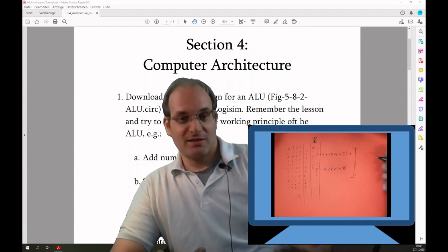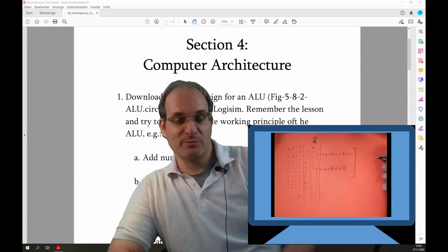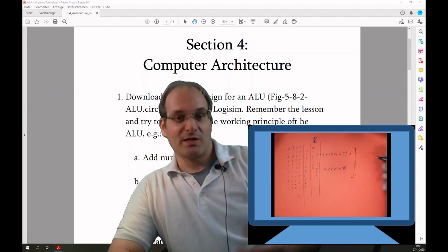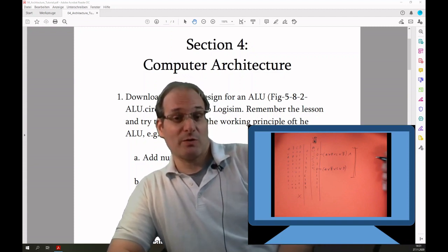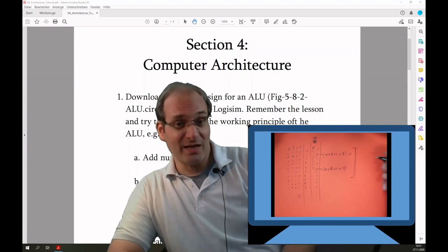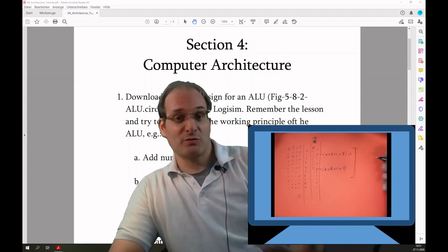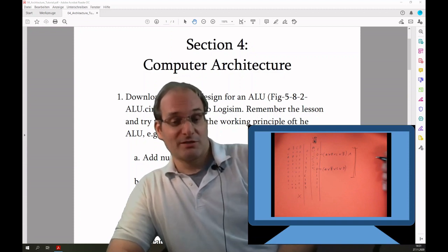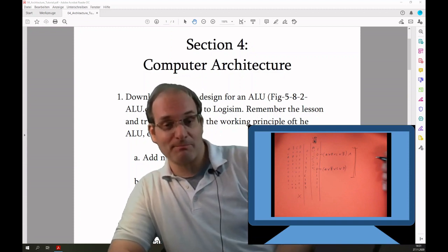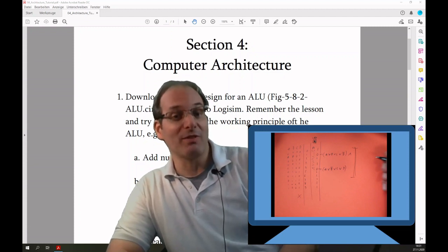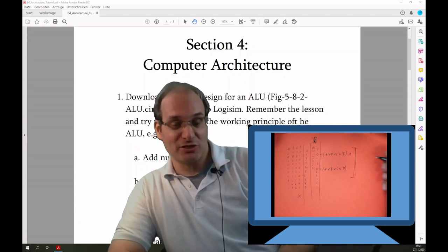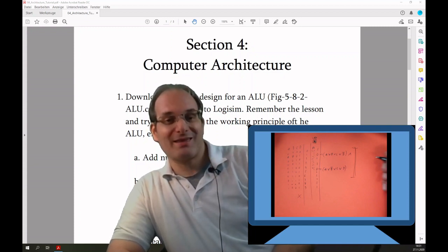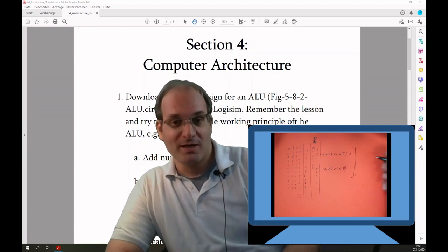If you reach the decimal 10, then the ones position in the base 10 system is 0 again. So the 7-segment display should show 0 again. In 11, you should have a 1, 12 a 2, 13 a 3, 14 a 4, and 15 a 5. So therefore, you should also have some truth table values at the positions from 10 to 15, especially if you make the conjunctive normal form.